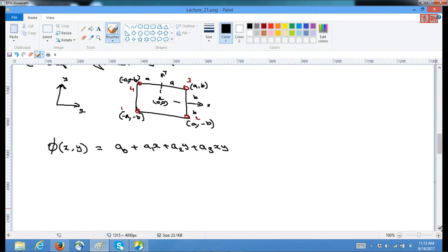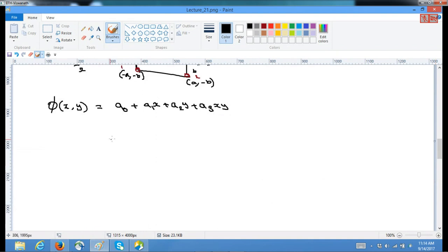Anyway, I have already proved it since I have these shape functions, but I'll redo it for the benefit of the audience. So we want to write this as phi i Ni, and it runs from 1 to 4 because there are 4 nodes. So this I can represent as 1 x y xy times a0 a1 a2 and a3.